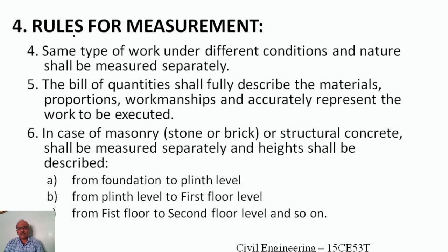By mentioning and describing where we have taken the measurements. For example, from foundation to plinth you are taking a column measurement, so you have to write foundation to plinth level, from plinth to first floor level, from first floor level to second floor level, and so on. This will be the same for the brickwork, super brickwork also, plastering also. The item will be the same, but we are executing at different stages, different situations, so those have to be measured separately.